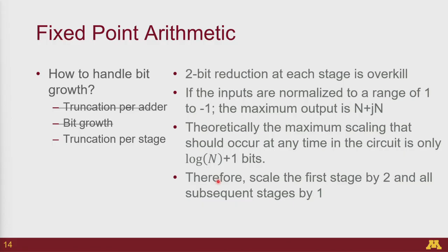So is everyone clear on fixed point arithmetic, truncation and scaling? These are some of the main issues which you'll face when you're designing the data path for the entire FFT.